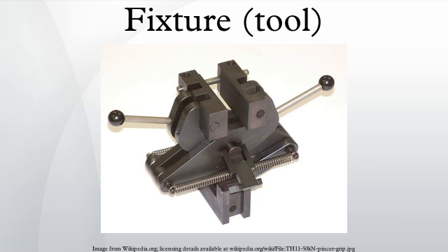To secure workpieces and prevent motion during operation, support components primarily use 2 techniques: positive stops and friction. A positive stop is any immovable component that, by its placement, physically impedes the motion of the workpiece. Support components are more likely to be adjustable than locating components, and normally do not press tightly on the workpiece or provide absolute location. Support components usually bear the brunt of the forces delivered during the operation. To reduce the chances of failure, support components are usually not also designed as clamps.